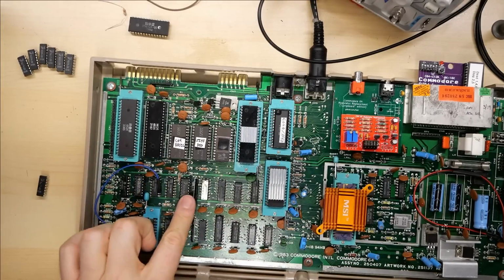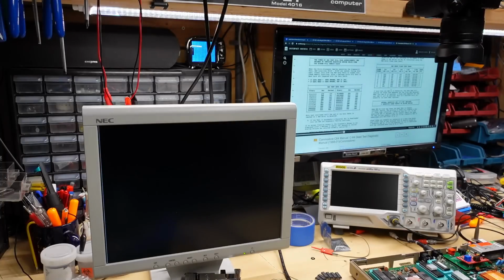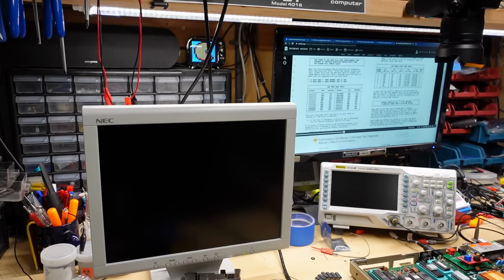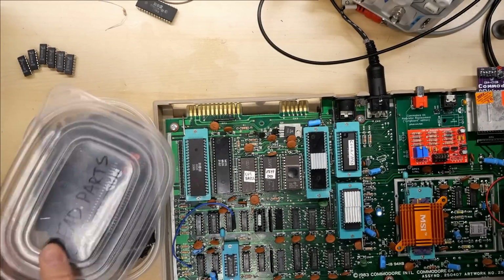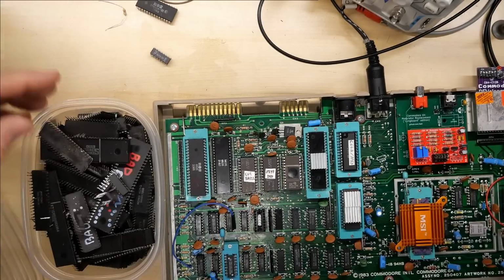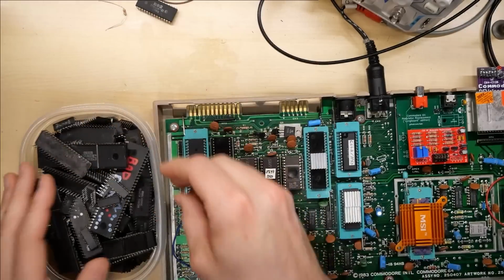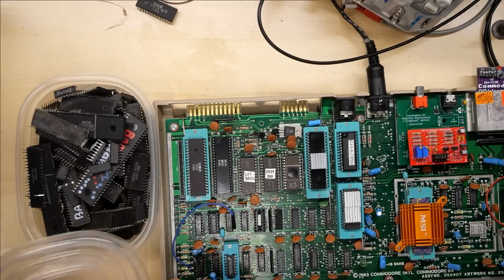So now the only bad chip is in here, which is U12. U12 is 1 flash. And we got 1 flash. Hey, again, dead test doing its job. Awesome. All right, so I have the dead parts bin here, and even though I know that 6 of these RAM chips are actually good, all of these are going into the dead parts bin, because I don't trust those MT RAM chips.